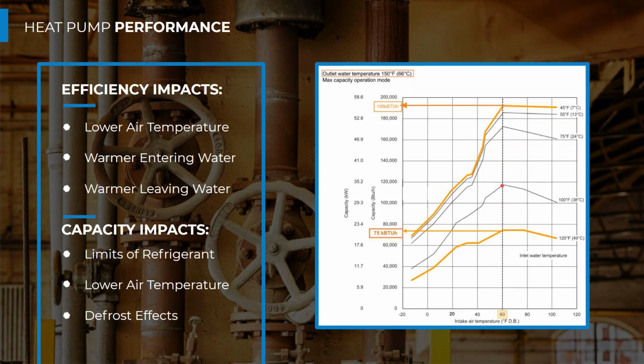Whereas when the inlet water temperature climbs, whether it's to 100 or 120 degrees, we're getting a lot less capacity into that heat pump, and we're typically putting the same amount of energy into it that we were up here. So we can maximize the efficiency of our heat pump water heaters by essentially using the full heat pump heat cycle, taking cool water and making it hot, and not taking warmish water and making it hot or operating on that upper end limit.